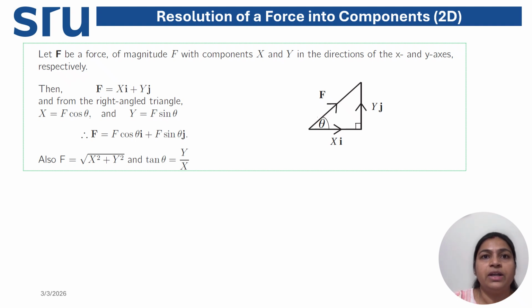So first, what is the meaning of resolution of a force? Resolution of a force is the process of splitting a single force into two perpendicular directions that have the same effect as the original force. So in two-dimensional analysis, one component is along the x direction and another is along the y direction.